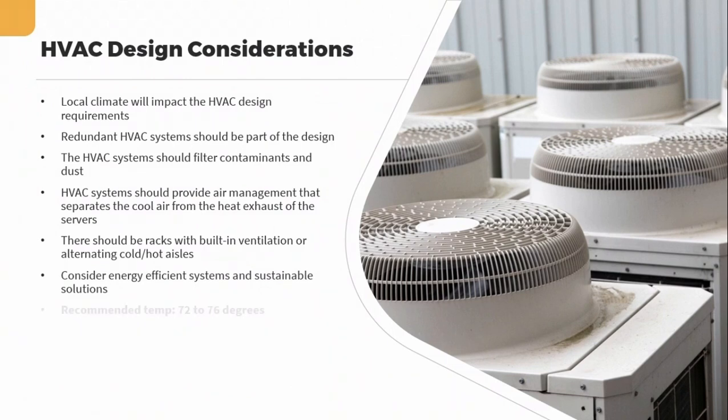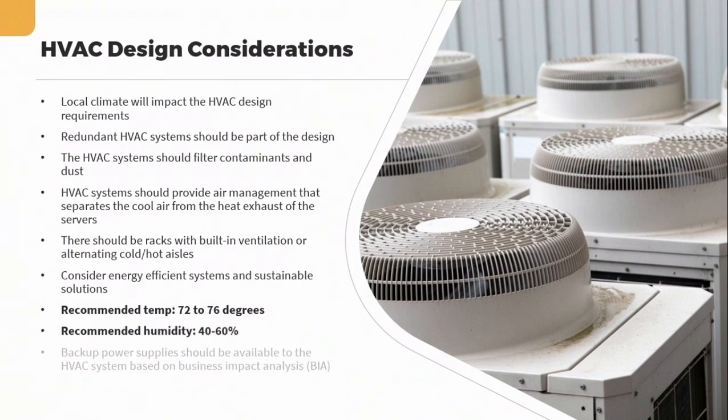On the exam, the recommended temperature, for example in the data center, is 72 to 76 degrees Fahrenheit. The humidity recommendation is 40 to 60%, and backup power supply should be available to the HVAC system based on your business impact analysis, BIA.